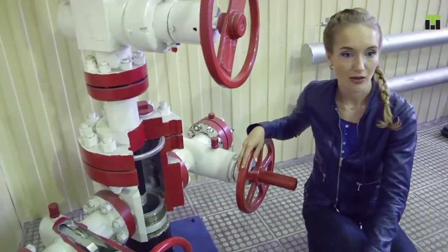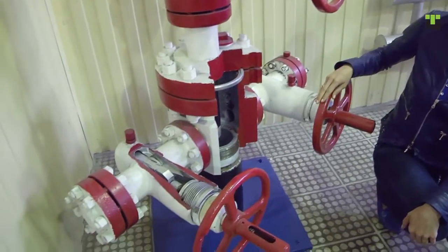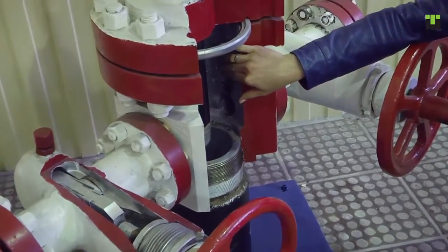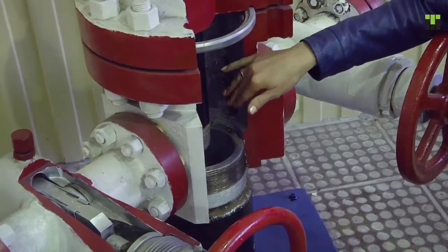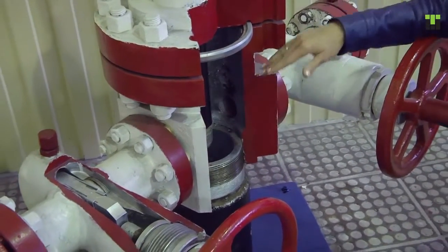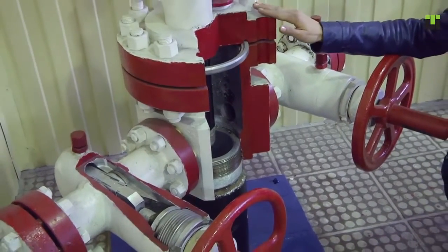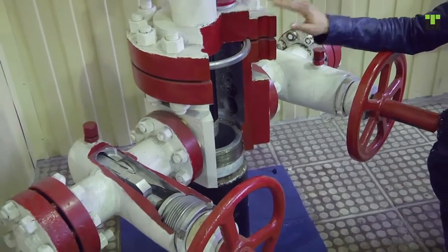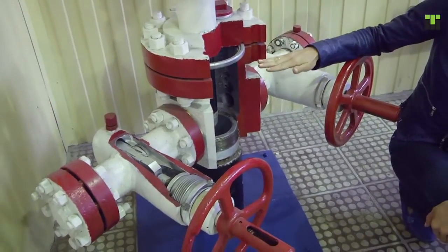The side outlets provide access into the annular space to inject water or killing fluid, to add hydrate formation or corrosion inhibitors, to withdraw gas, and to attach a manometer when we need to measure the annular pressure. Tube hanger is installed directly on top of the tubing head.